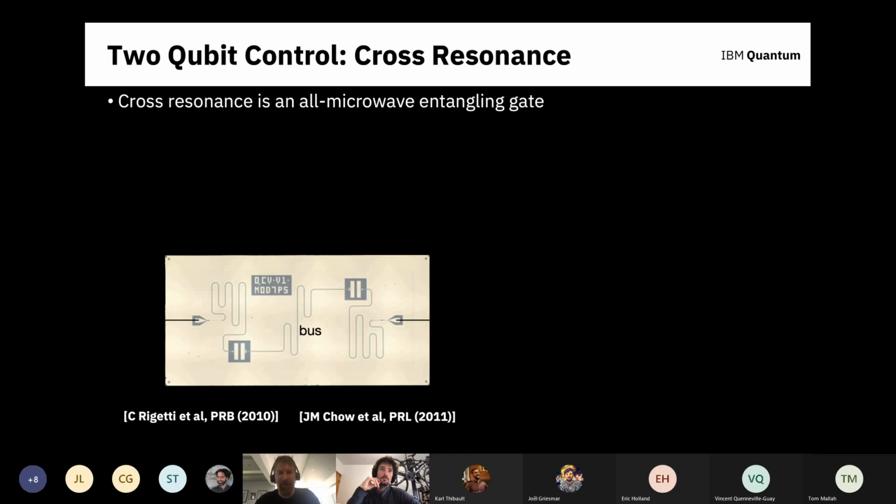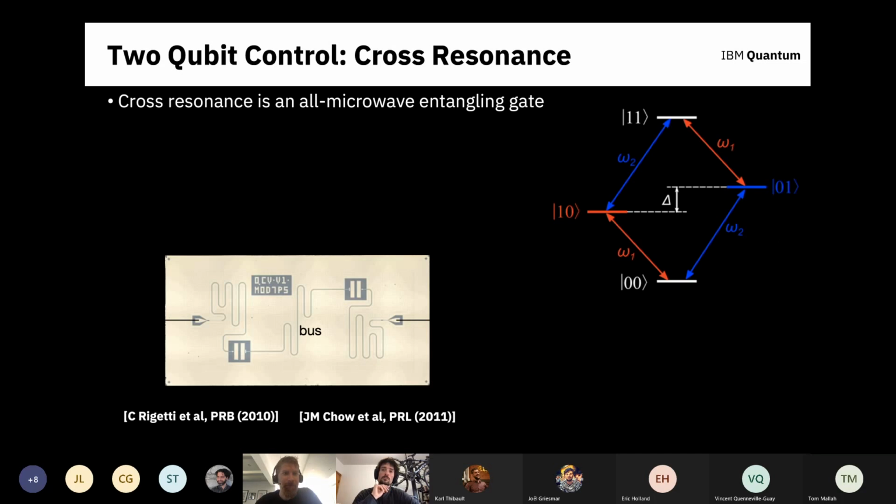By fixed frequency transmons, I mean they have no loop in them in which you can tune the frequency of them. It's a single Josephson junction, and due to the natural spread of forming this glassy Josephson junction, which changes the critical current, which in turn changes the frequency of the qubits, we get a natural variation in frequency between those, which is necessary for the cross-resonance gate. But we don't have any extra control knobs, and that's why we really like it.